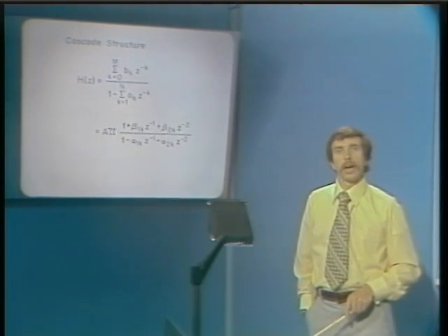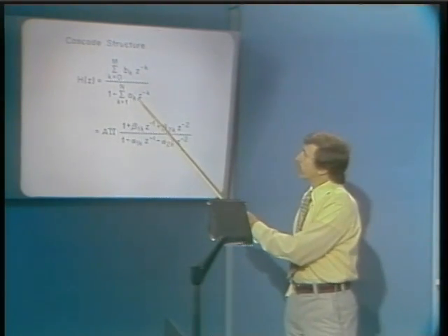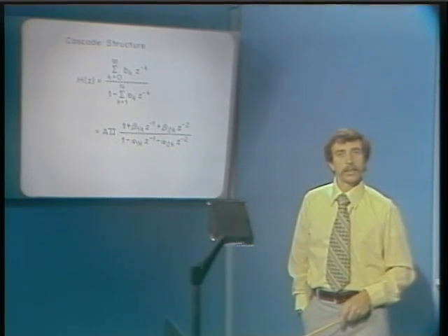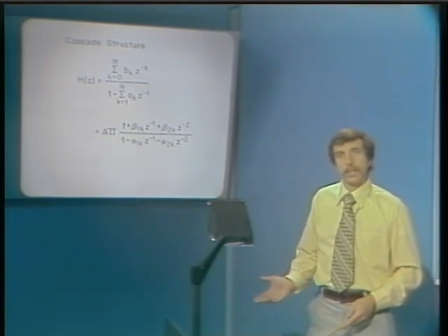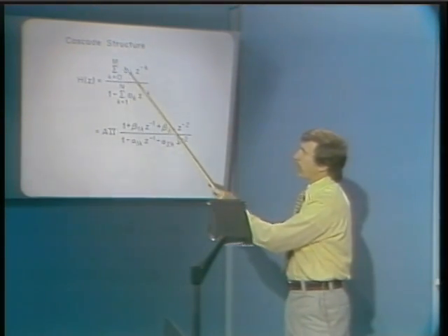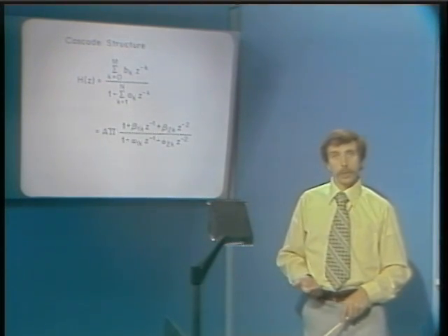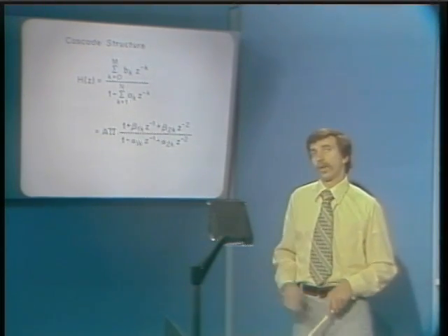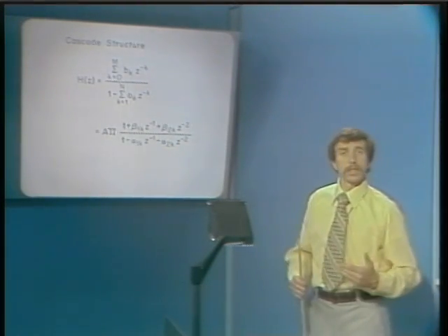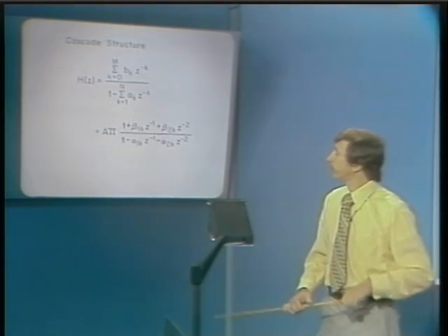system on a digital computer or with special purpose hardware, we're faced with the problem that these coefficients can't be represented exactly. If we have, let's say, an 18-bit fixed point register, we're restricted to truncating or rounding these coefficients to 18 bits. If we implement a filter in special purpose hardware, we might want the coefficient registers to be as low as 4 or 5 or 6 or 10 bits. Obviously, the more bits, the more expensive the hardware implementation is.